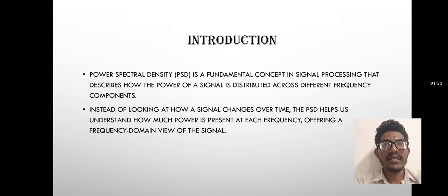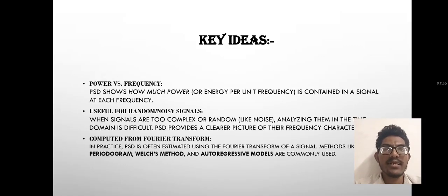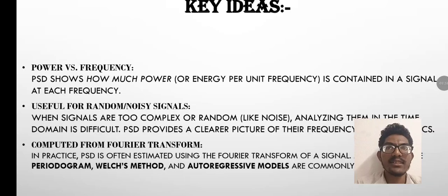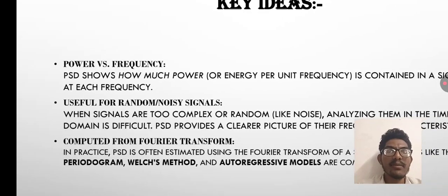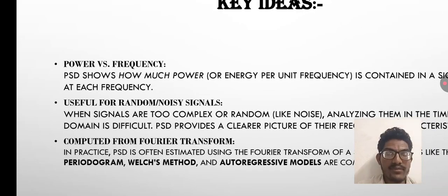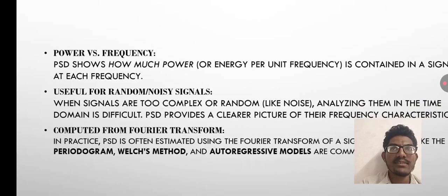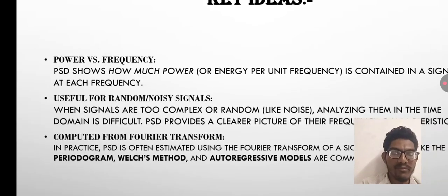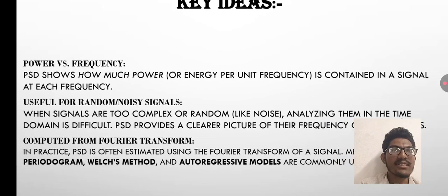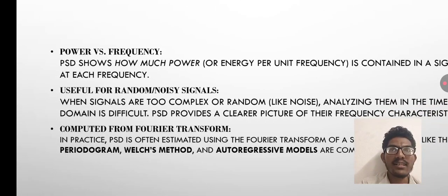Next, the key ideas about the power spectral density. Mainly the power spectral density is based on two components. One is power and another is frequency. PSD shows us how much power or energy per unit frequency is contained in a signal at each frequency.